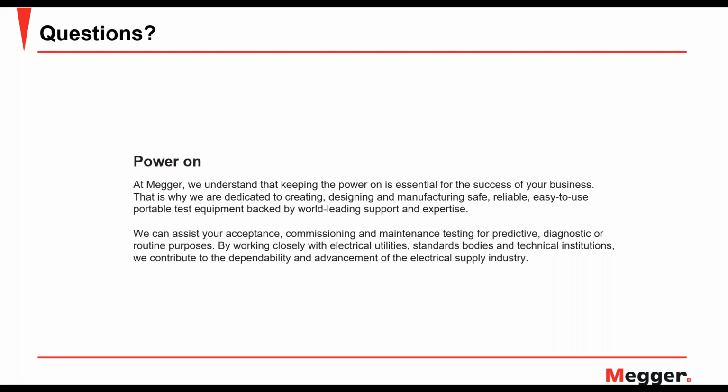The interwinding SFRA measurement, the capacitive, I should be specific because there's a capacitive interwinding and an inductive interwinding. The capacitive interwinding SFRA test essentially provides the capacitance information that you would get had you done a power factor dissipation factor test. So that can always be used, of course, as a backup if you suspected winding deformation.